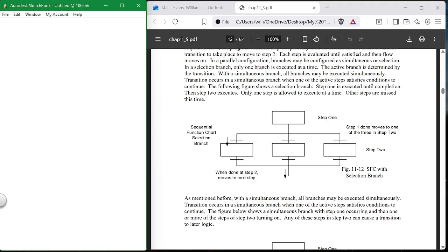Now, if you're in this state, you're not executing these states. If you're in this state, you're not executing any of these three states. There's logic in each of these states, okay? Now, if there is safety logic in these states and it's not being executed, what happens? That safety logic is not happening. It's not being exercised. So you have to be extremely careful, all right?